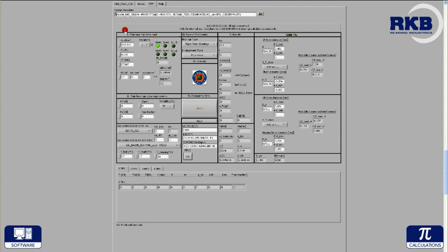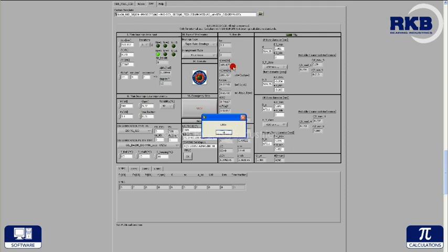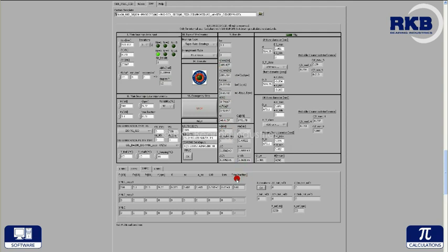From the software interface, the 3-step iteration button is selected, and each step is inserted as an individual working condition case. The data for the first operational step is inserted: the radial and axial forces in kilonewtons, the rotational speed in RPM, and the time fraction in percentage. The first step is executed, and the calculated values according to ISO are filled in the first subarray table.